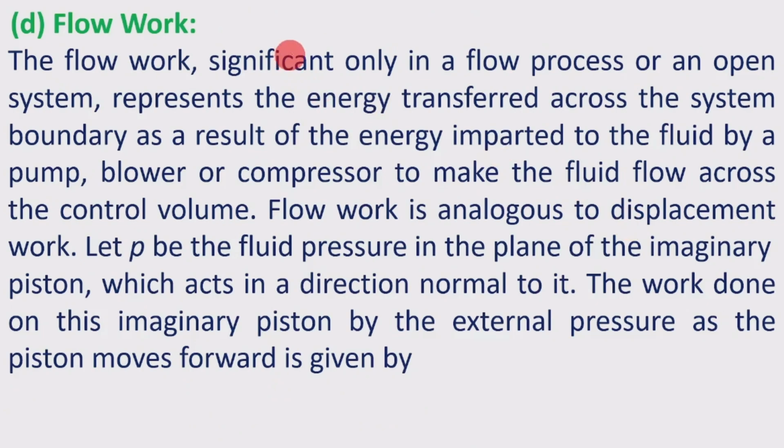Then next one, flow work. The flow work is significant only in a flow process or an open system. It represents the energy transferred across the system boundary as the result of energy imparted to the fluid by a pump, blower or compressor to make the fluid flow across the control volume.